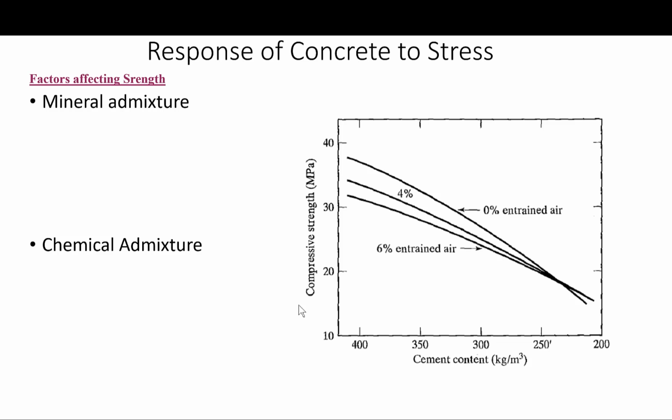The other major pozzolan, silica fume, is generally used to increase strength and will do so even at the same water cement ratio. Silica fume not only combines with the calcium hydroxide resulting from the hydration of C3S and C2S, but also fills in voids between the cement particles, reducing the flaw size available for crack initiation.